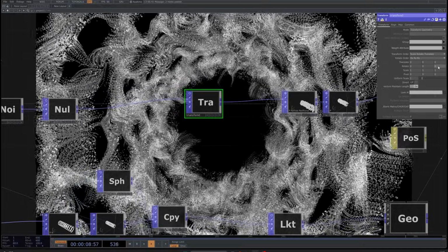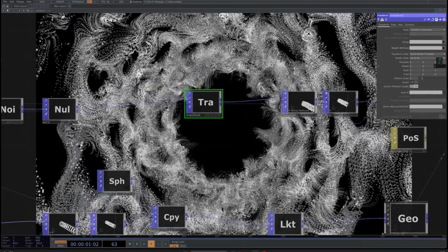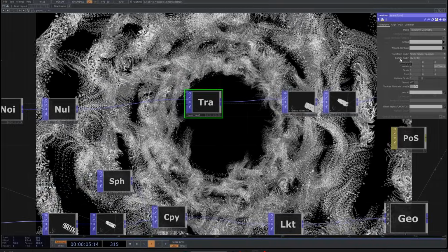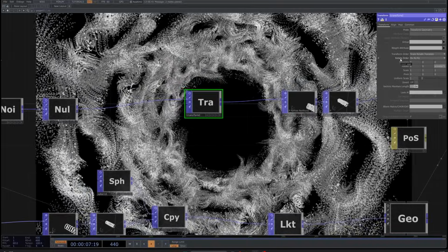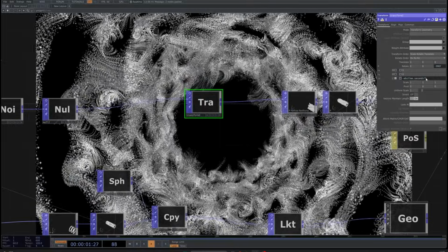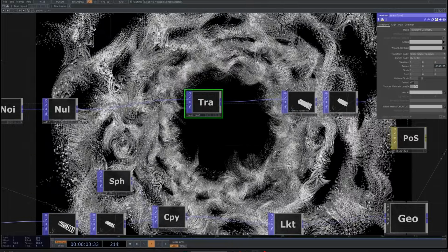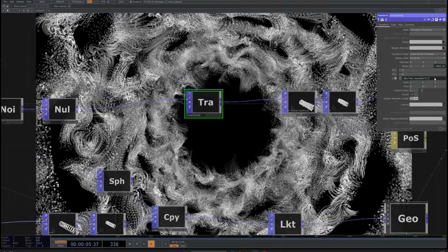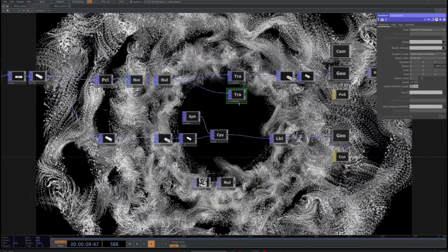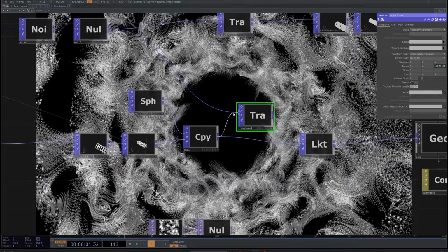And in this transform, I'm going to use rotate on the z-axis to create some movement. So I'm going to use minus absolute time dot seconds multiplied by 5, or multiplied by 2.5. And I'm going to copy this pop and put it in this system.